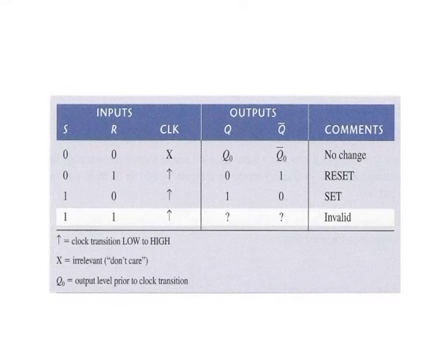Remember, the flip-flop cannot change state except on the triggering edge of a clock pulse. The S and R inputs can be changed at any time when the clock input is low or high, except for a very short interval around the triggering transition of the clock, without affecting the output.